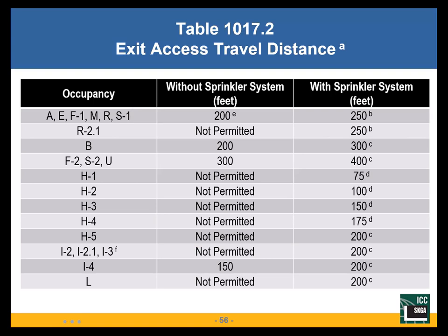Well, how far can I go? It depends. What's the occupancy of the building? Is the building sprinklered, which gives me more time to exit? Let's pick an A occupancy now. Not sprinklered, 200 feet to the exit or to an exit. If it's sprinklered, 250 feet.